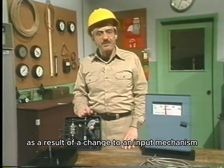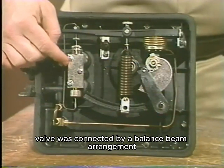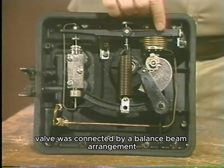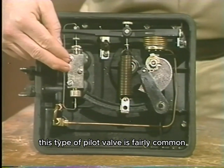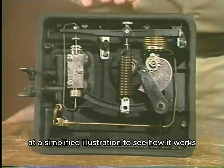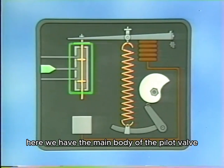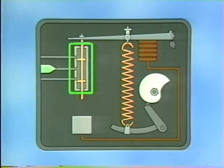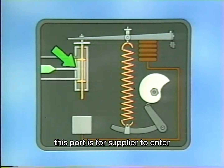In this positioner, we saw that the pilot valve was connected by a balance beam arrangement to a bellows input mechanism. Now, this type of pilot valve is fairly common. We can look at a simplified illustration to see how it works. Here we have the main body of the pilot valve. It houses the back pressure compartment. This port is for supply air to enter.